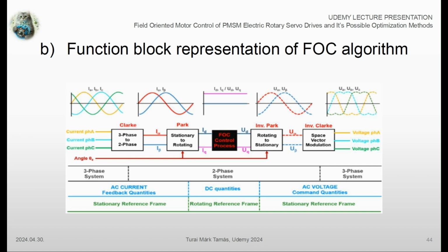After the three-phase voltages are fed to the electric rotary machine, phase currents are going to flow that we are measuring in the next iteration of the FOC algorithm. As you may see, the above-mentioned steps are repeated constantly with a certain time period. This is called the task time. The algorithm is manipulating the phase currents according to the given input of the user.